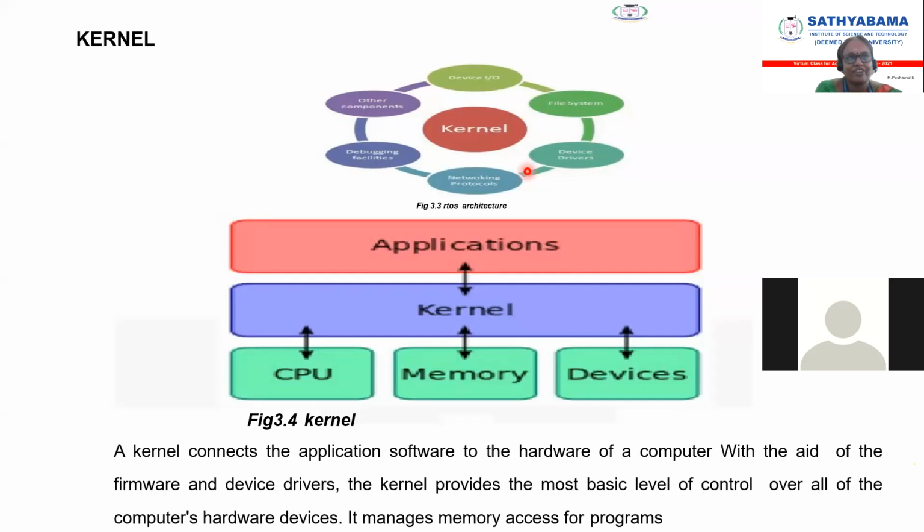And device drivers: I told you yesterday one thing. One vibration sensor is there. If any accident happens, definitely it will alert the microcontroller. But sometimes the output of the vibration sensor is very low, so I have to go with some amplifier. Then only it will drive the microcontroller. Or else, when I want to interface any motor with a microcontroller, I always need an interfacing IC. I have told you, in the stepper motor, I can't directly connect with the microcontroller. I need some interfacing IC. So that is called a device driver.